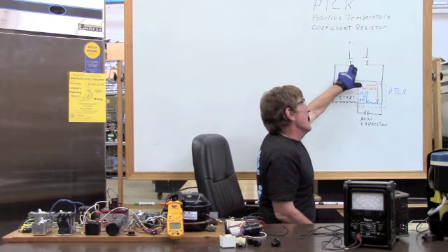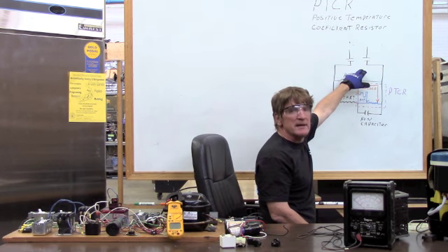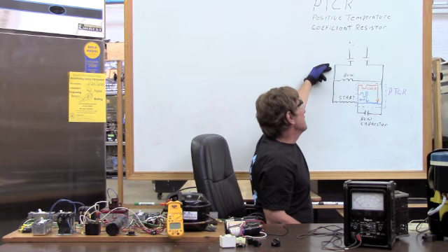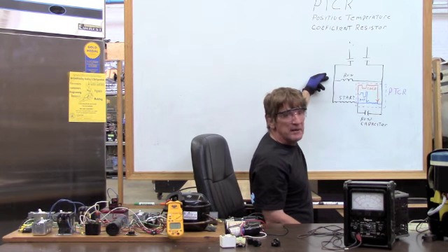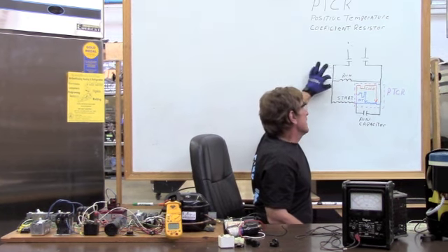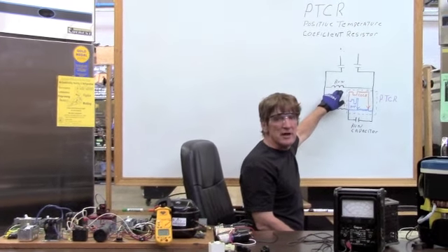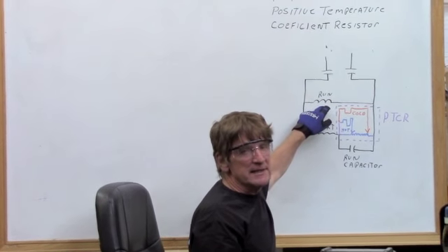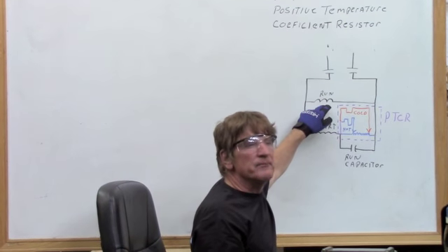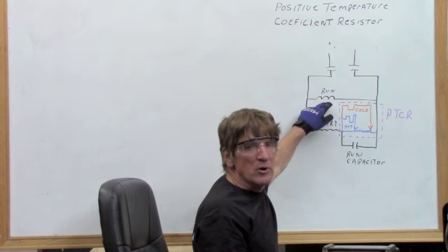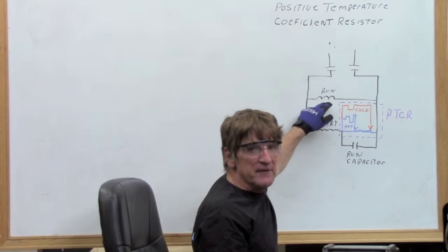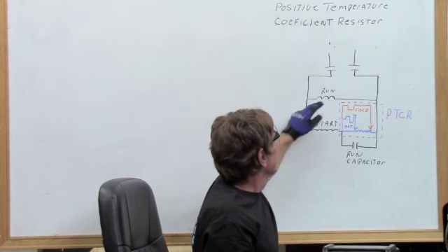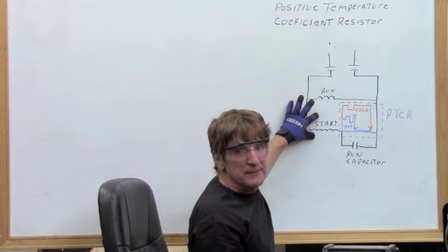we can see that we have our start components, which could be a thermostat, a contactor, whatever it happens to be. We have my common. So when I close these set of contacts, I'm going to energize my run winding, but the compressor will not start yet because it needs that offset current going through the rotor to give it a slight phase shift to get that motor going in the right direction. So we need our start winding.